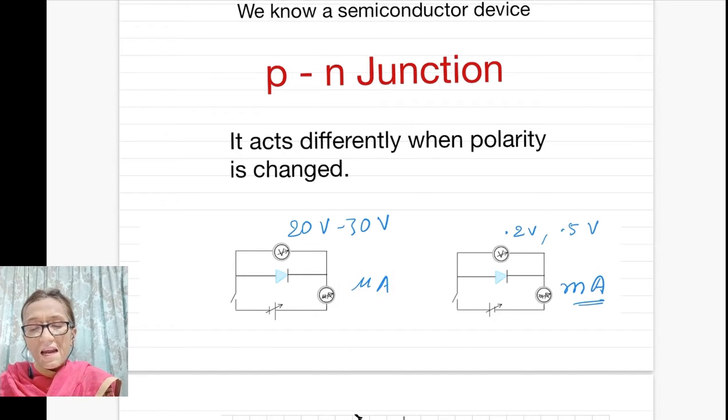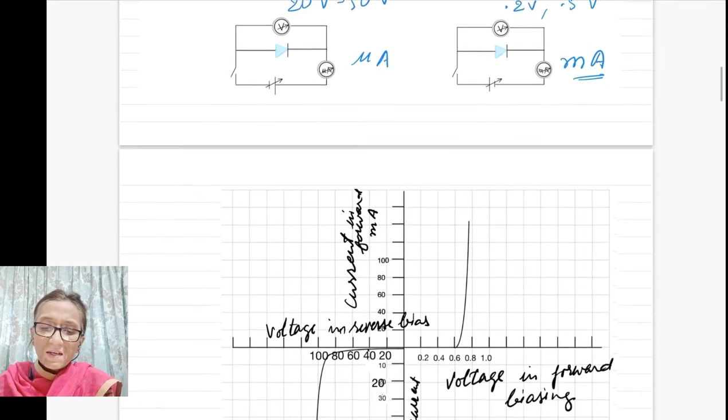This current can be considered negligible, you can consider it as zero. So in forward biasing, when current is flowing along one direction, the semiconducting diode allows current through it and a circuit can be made. But in reverse biasing, current is very small. You cannot even notice it when the ammeter is of milliampere range. So we consider that no current flows in reverse biasing.